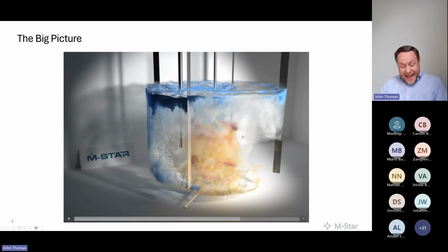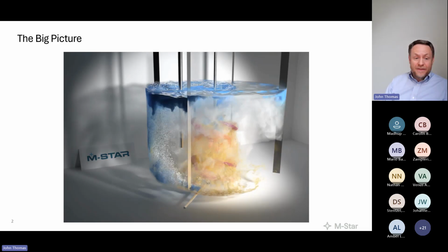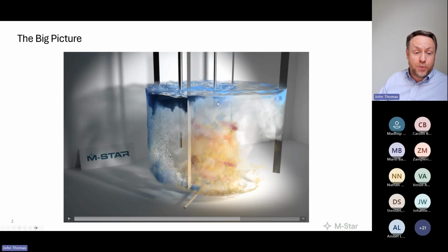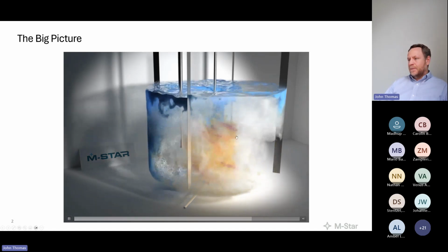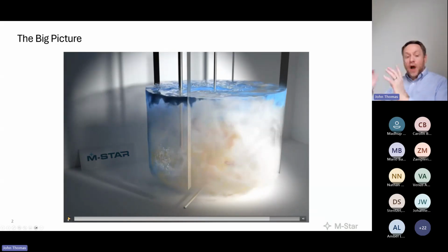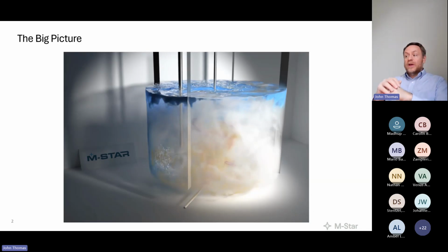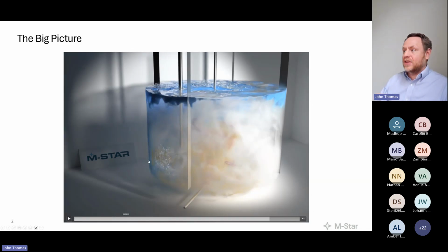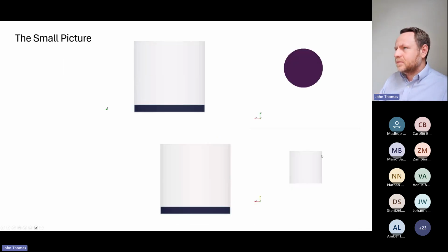Because what we actually think KLA is at a small scale, or what we think the effective mass transfer rate was at a small scale, may not be what we're realizing at the larger scale, due to the depressed effects of the free surface at larger scale as this volume becomes bigger. We'll speak of this in detail, but this is the big picture. There are multiple ways in which oxygen or CO2 can intrude into an aqueous phase. We're going to tease those apart today and understand how we can attack this problem at different scales.